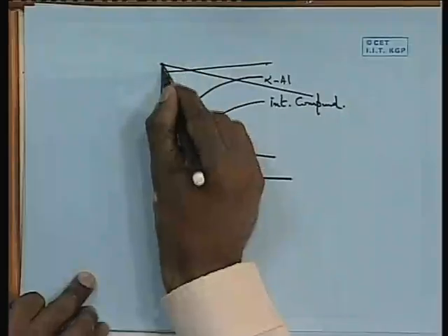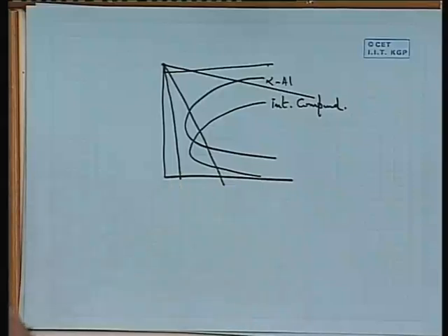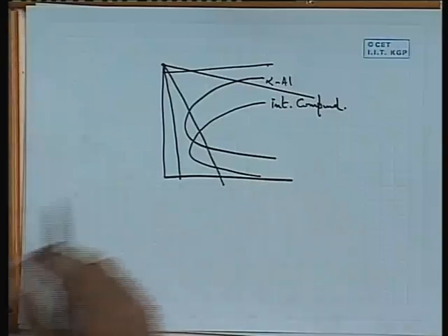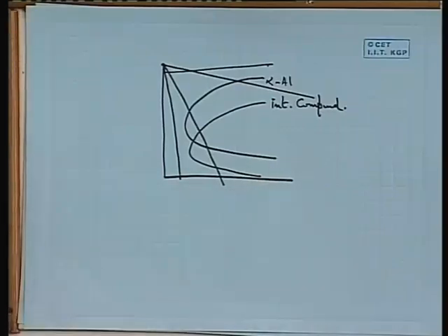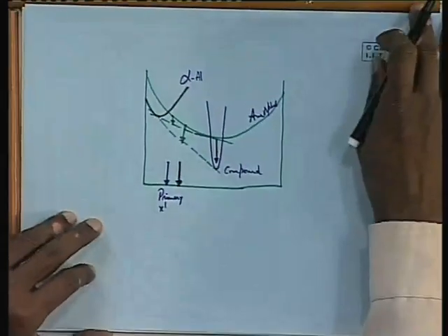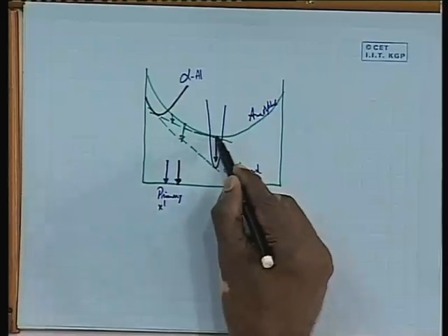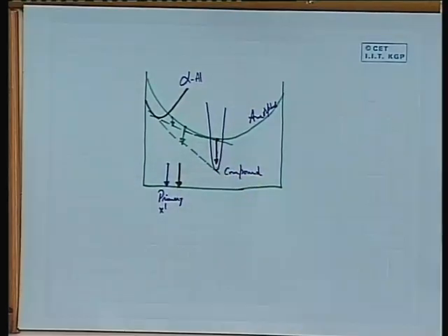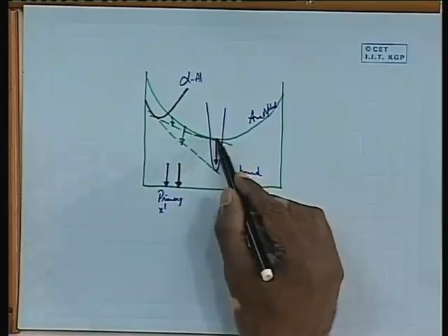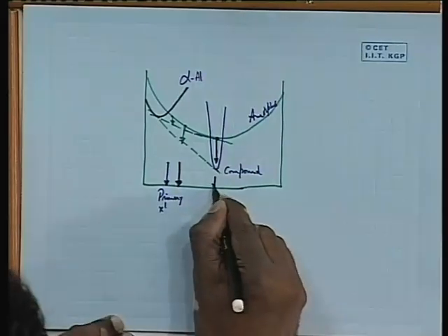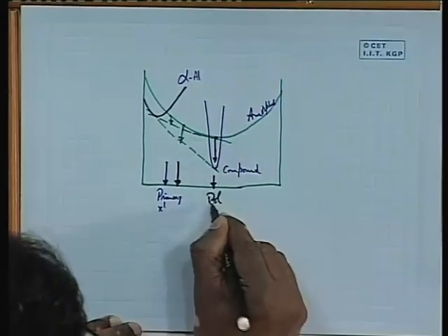And in addition, if one cools it very rapidly, you can get an amorphous phase and start crystallizing this amorphous phase. And when you crystallize this amorphous phase, depending on the composition that you choose, you can have various possibilities. For example, if the composition of the amorphous phase is exactly the same as that of a compound which is possible in that system, you will see that the amorphous phase transforms to the compound by what is called polymorphous crystallization.